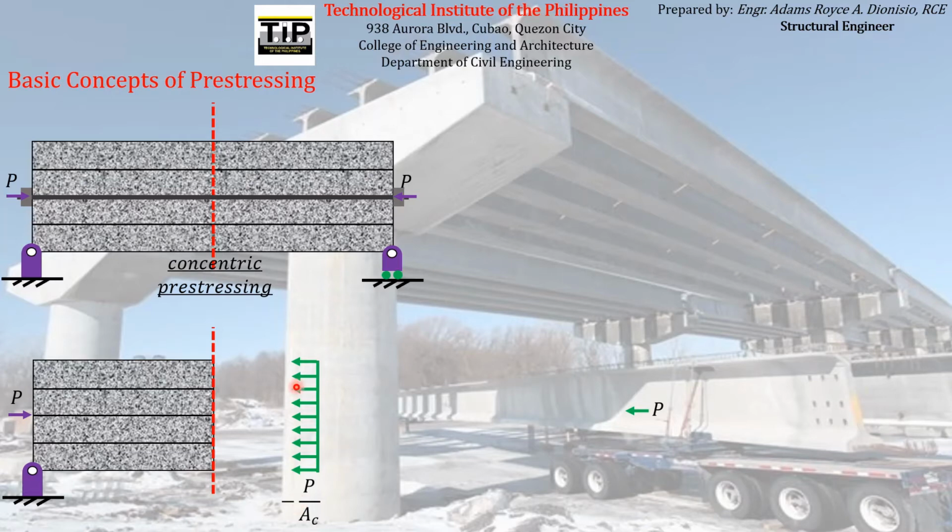So that is the effect of the concentric pre-stressing on the concrete beam. It produces what we call internal stresses. Actually, it's called compressive stresses, which are uniform, with a magnitude of negative P over A sub C.